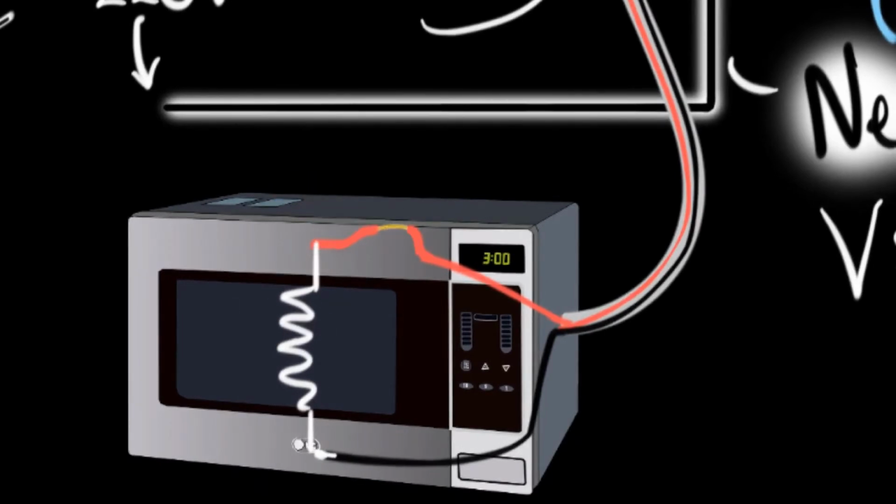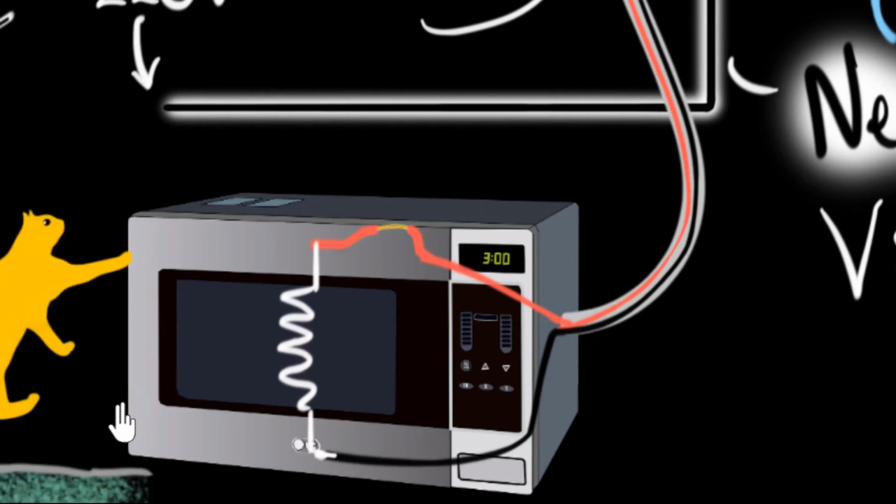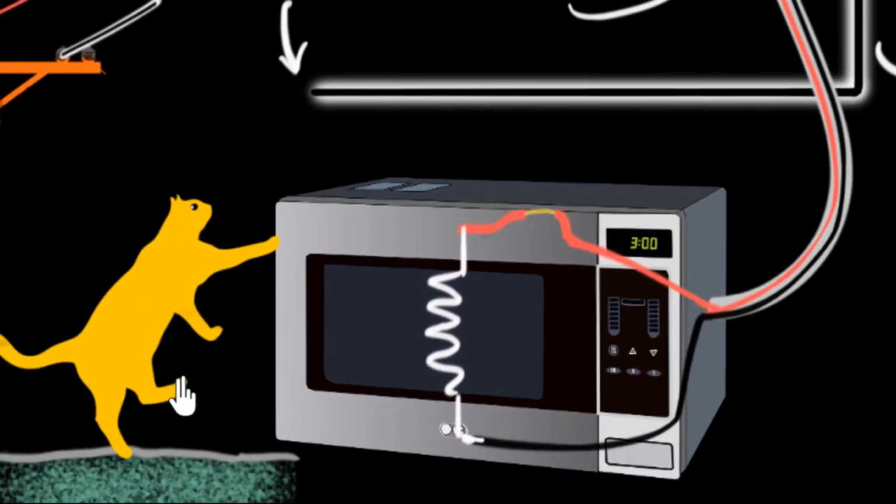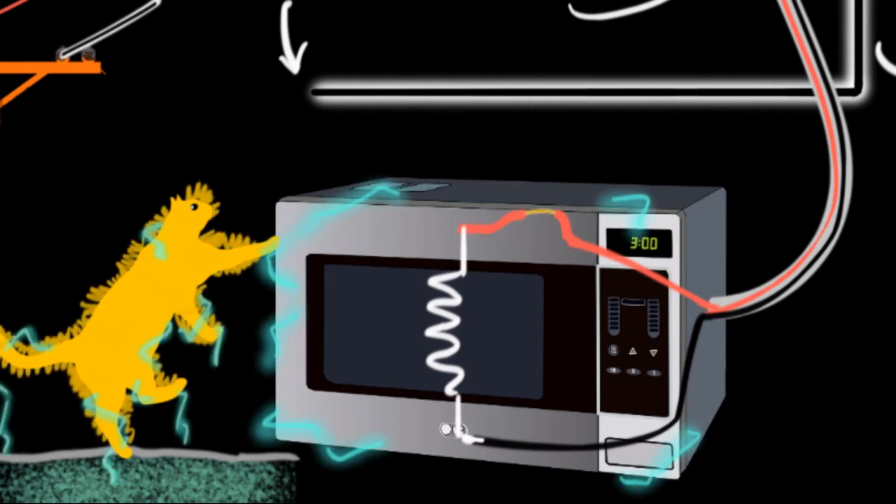Now, again, let's bring back our kitty. She's gonna have a bad day today. If I switch on the plug now, what do you think is gonna happen? Well, because the live wire is touching the metallic case and metal is a conductor, electricity will start flowing through the metallic case, through the cat and into the ground, again giving our cat a very, very nasty shock.